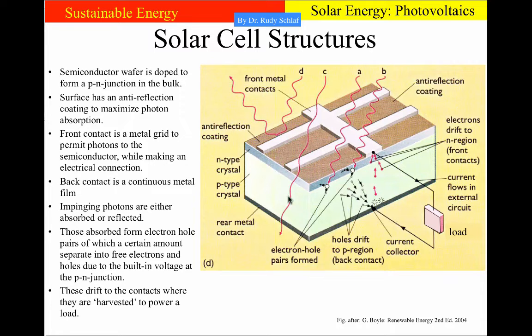So essentially we have the semiconductor material that absorbs the light and separates the electron-hole pairs. Here in this example there is a p-type wafer that has been implanted with n-type dopants to create that p-n junction here at this interface. The light is absorbed from above. There is an anti-reflection coating to maximize the number of photons that make it inside the semiconductor material.